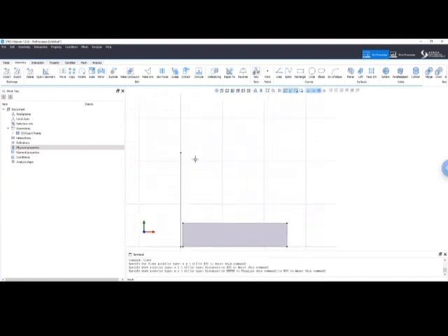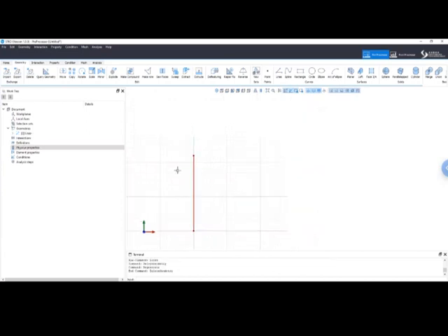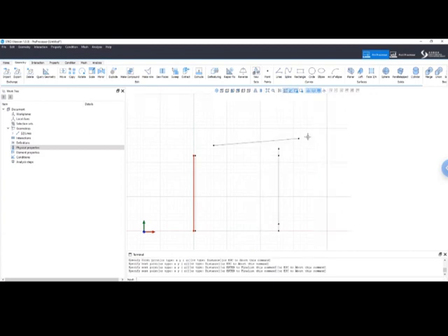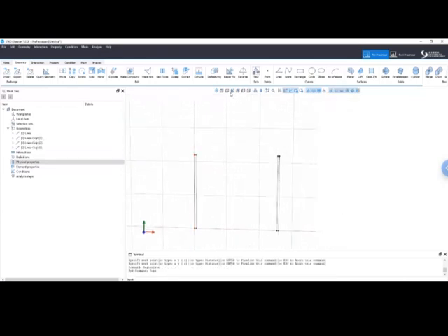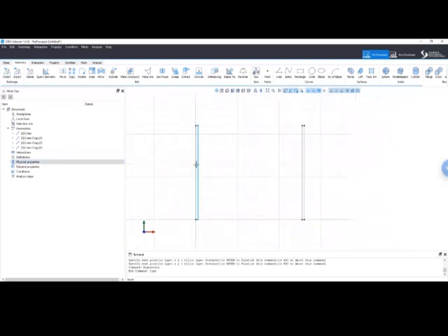Here. Actually, I don't need this one. I'm going to do it in a different way. So let me take this one and copy it. Half of the mortar thickness, so 5 millimeters. Then the brick thickness, 250, sorry. And then the other half of the mortar joints, so another 5. Why am I doing this? Because I need to create the other bricks on the top, and they are based on these dimensions.